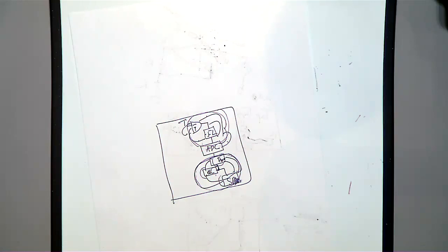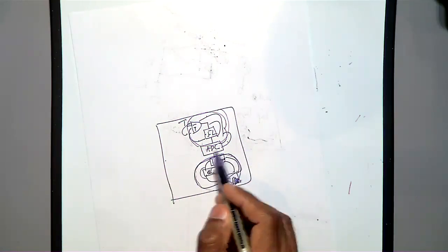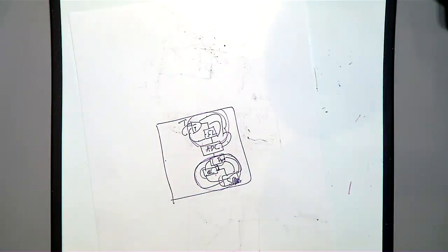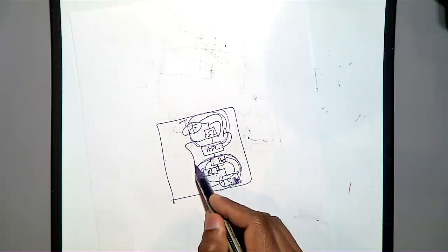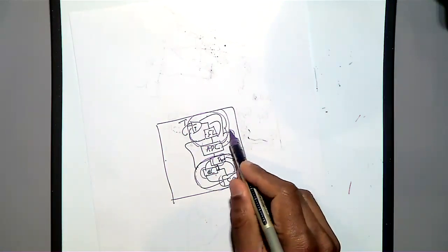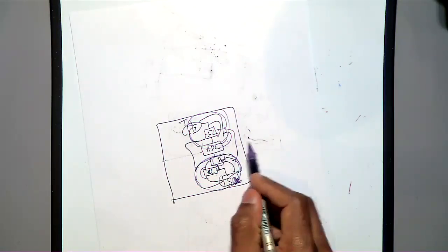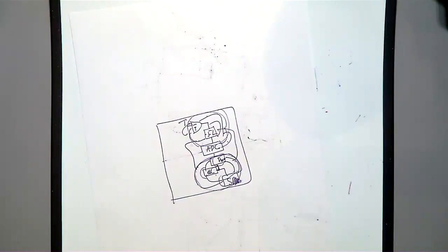So in that case, even if you are not splitting, you don't need to split the ground plane. Here it is fine, you are okay to some extent. But in your design, if this signal is crossing to the digital plane for some reason, you know what I meant? If the design is getting complex, then you have to split your ground plane. If your connection is only through the ADC, even without splitting it is okay. Not great, but it will do your job unless you are using a very high resolution ADC. Then your pins might jump. Otherwise, even without splitting, people design it.